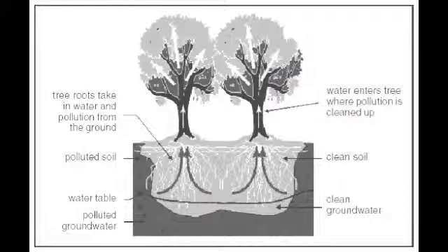Phytoremediation is where plants facilitate bioremediation by taking up and incorporating contaminants into plant biomass, immobilization or phytostabilization of contaminants in the subsurface, releasing enzymes into the rhizosphere to act on contaminants, or stimulation of microbial-mediated degradation in the rhizosphere. This method is a relatively new concept that has yet to be proven in the marketplace. However, the potential is of great interest.